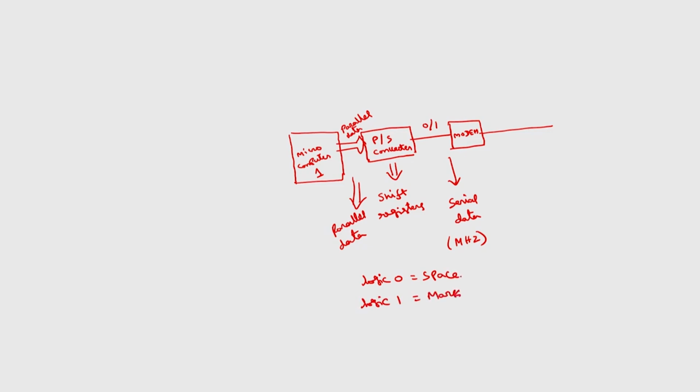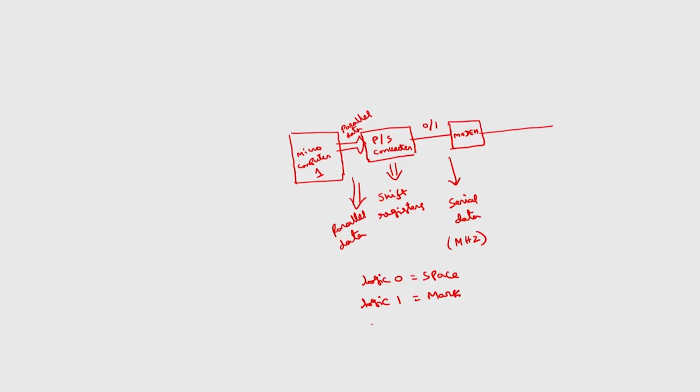There are different types of modulation schemes that can be employed in a modem. If I use frequency shift keying, FSK, logic 0 (space) will be represented by one frequency, say F1, and logic 1 will be transmitted with another frequency F2. Normally these will be 1070 Hz and 1270 Hz.